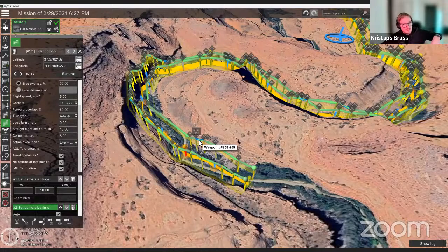So the drone stops, then flies forward, backward, and then continues on the route. These segments are inserted exactly as specified by the manufacturer, so either every 100 seconds or every 1,000 meters, whichever comes first. In case, I know there's some of you who like to adjust these parameters, these can be adjusted in a configuration file we have. So if you want to, you can get in touch with us and we can also explain how you can do that if you want.